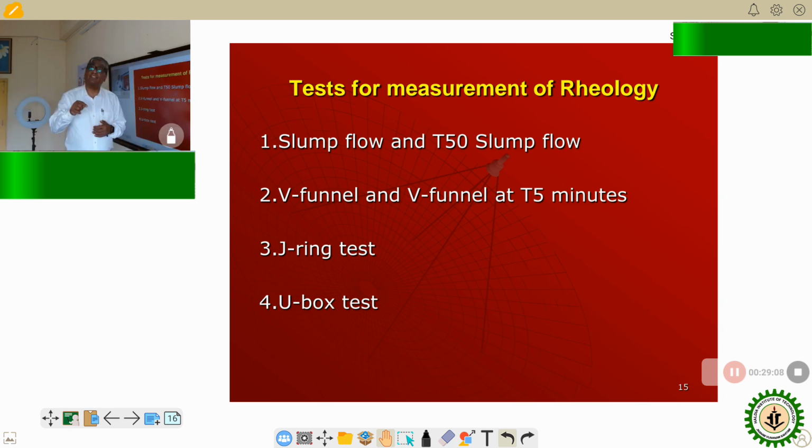And you can measure it also. How? If you have a rheometer, then you place your concrete in the rheometer, and it is connected to a computer and it will give you some graphs and other things that I am not discussing in detail here, and you will get the viscosity level. So if it is within your expected level, fine. Otherwise, you have to revise the concrete ingredients, proportion, etc. to arrive at a particular viscosity level.